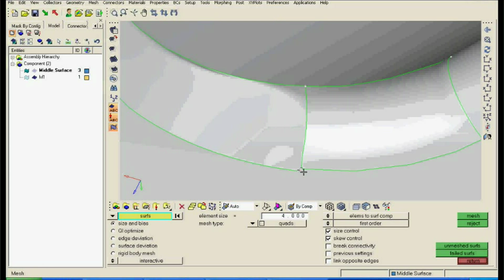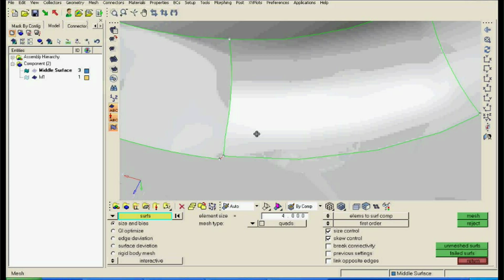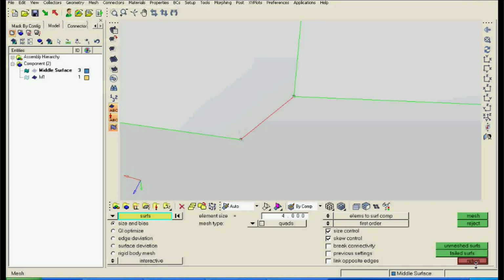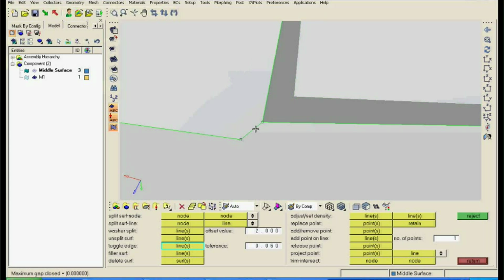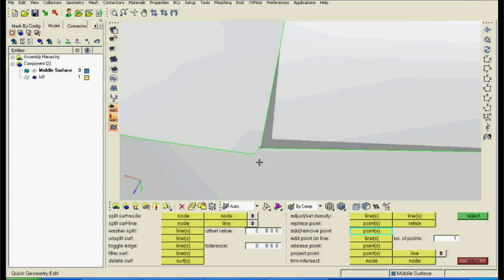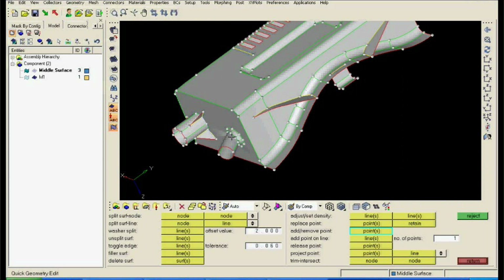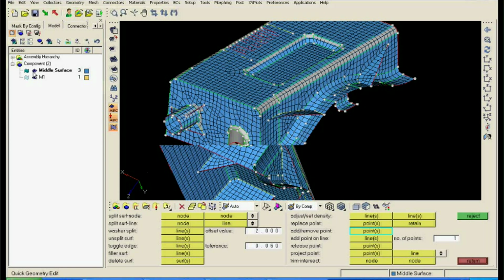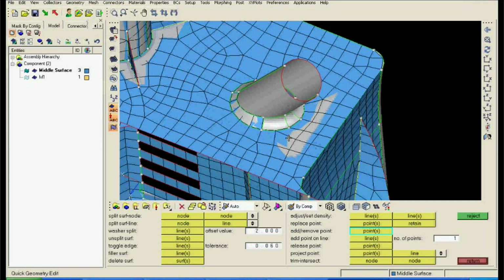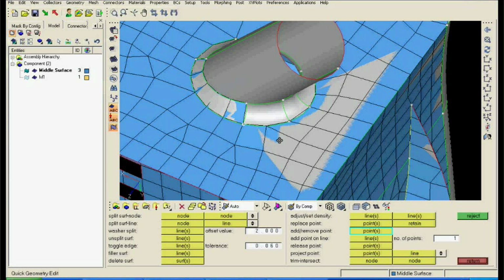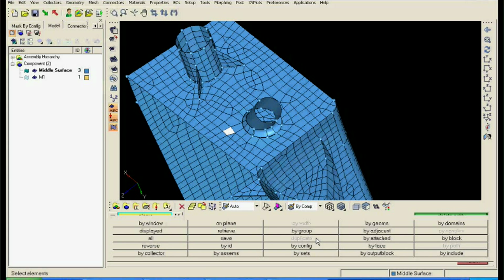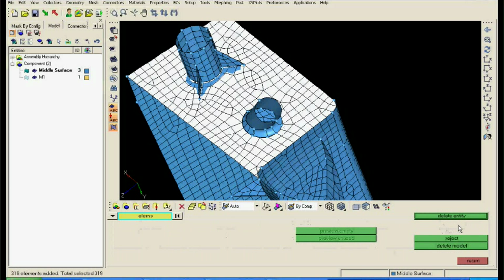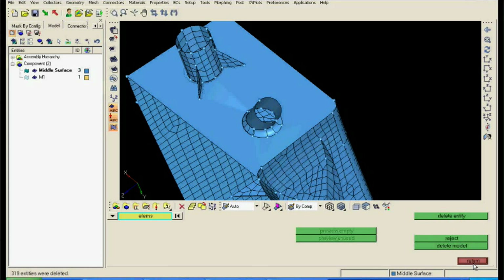This kind of small thing can come beyond your visualization. So that's why it's always good practice to hide the shade edges and make sure your model and everything is good. Otherwise you can also lead to such kind of mistake. So that's why it's not a good practice. For safety, I will just remove these face elements, and I can think of remeshing them again to make sure that we don't have any problem with that node. So again just working on the remaining surfaces.